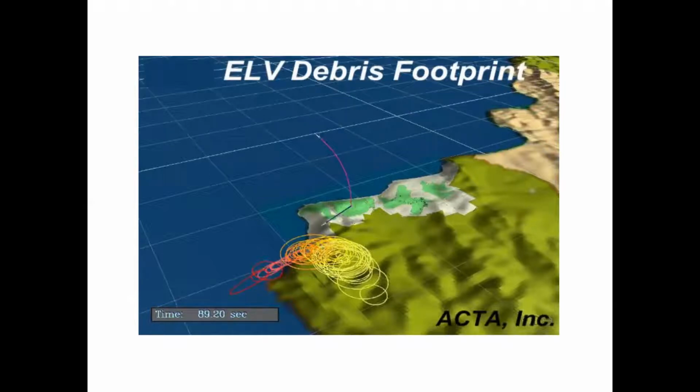The vehicles pick up enough velocity that the high ballistic coefficient debris is well out in front, and the low ballistic coefficient debris would be blown, in this case, cross range and away from the present position of the vehicle. Could you get it to play out to close to 120?